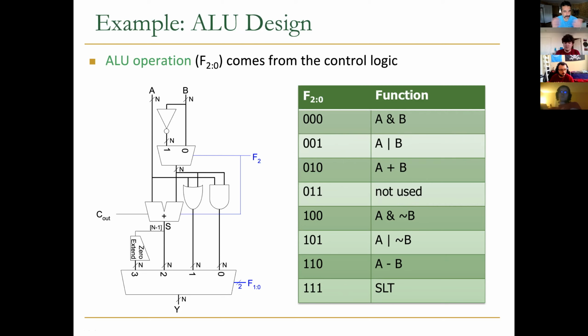So here, how many logic gates do you need? You need an AND, you need an OR here because you also need to implement OR. You need one mux here, one mux, two muxes here, and one adder here, and by adder, you already know that you can do A plus B or A minus B by negating B. And here is reserved, right? So this one is not used. This is also reserved. Do you have any question about this interpretation?